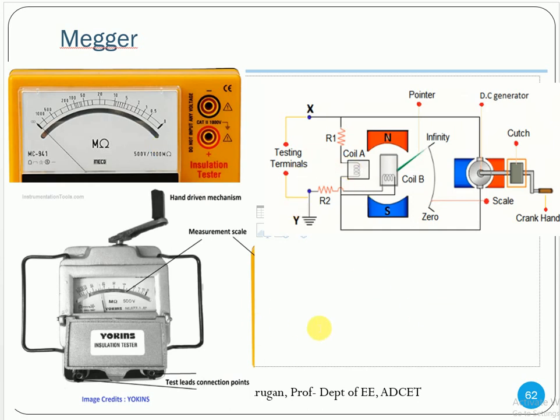So here one cable end is connected, the other cable end is connected, and here is a rotation, like that. If you rotate it, through the ohm reading you see the wire resistance. Whether resistance values are present or not present, or the wire is broken, everything can be easily determined with the help of the megger. For example, you check motor insulation.